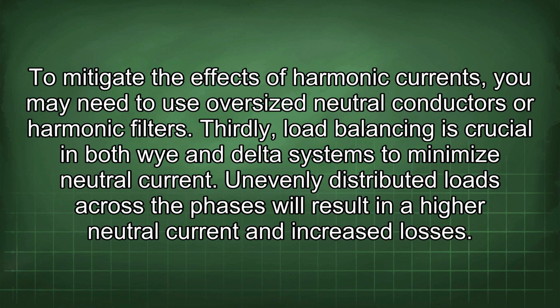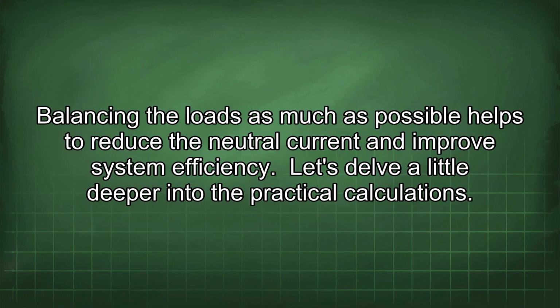Thirdly, load balancing is crucial in both Y and delta systems to minimize neutral current. Unevenly distributed loads across the phases will result in a high neutral current and increased losses. Balancing the loads as much as possible helps to reduce the neutral current and improve system efficiency.